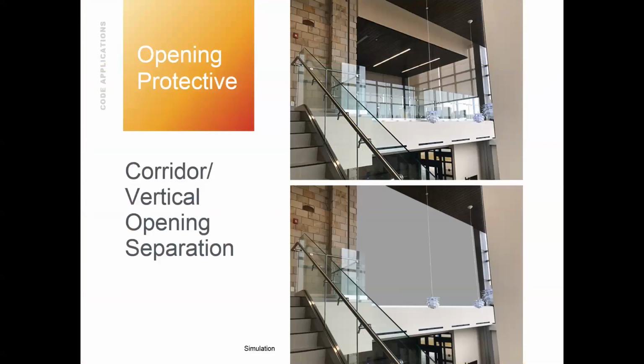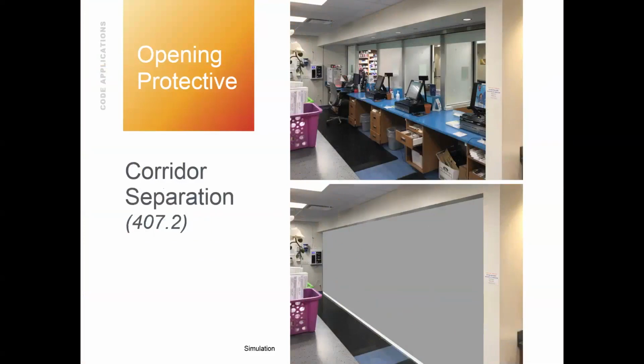So that's it. Fabric product closes off that waiting area that was up here. They wanted the sunlight to be able to come through, wanted that to maintain open. So once again, it carries that 20-minute rating in the waiting area there. Here's another interest in trying to create that 20-minute rating along the corridor. And God forbid that drawer were open when this thing is full. Come on, what are you thinking? Don't you know that there's a curtain overhead? But like we were talking about, that bulkhead's really limited. It's small. Less than 10 inches is what we commonly see for this fabric product we use. But once again, based off of the applications, it makes sense where it's only a 20-minute rated separation. So that's what we see in this corridor as well in the I-2s.